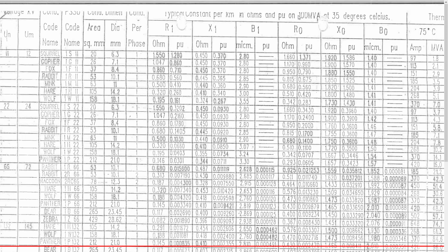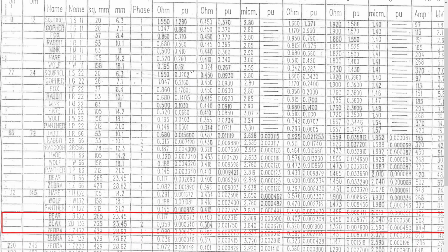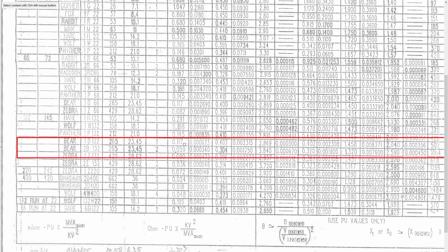And these parameters were tested on a 100 MVA per unit system with a 35-degree ambient. So basically not the typical winter. These parameters might change depending on the weather. Those values are for a 35 degrees ambient, so basically summer. In winter, you should be expecting different parameters. Okay, so now you know where we got the values.